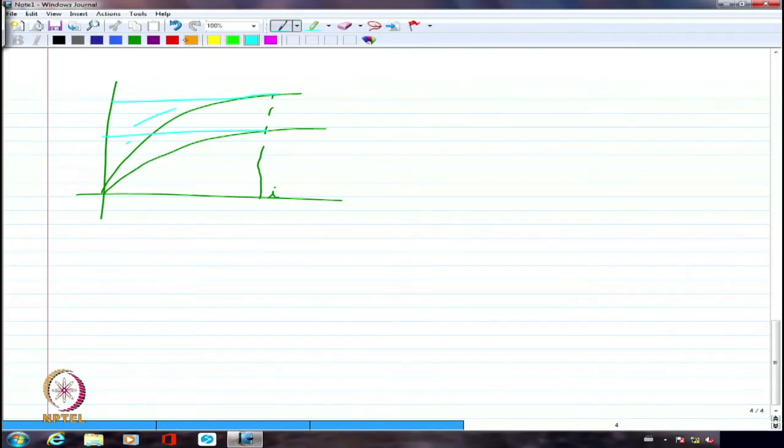So this particular area, which is enclosed by the two curves, if I call this OPQ, essentially represents my actual value of mechanical energy that has been outputted by the system. So the mechanical energy output that has come out of the system when the movement has taken place from x1 to x2 corresponds to this area. Now we'll have to check what this area really is.